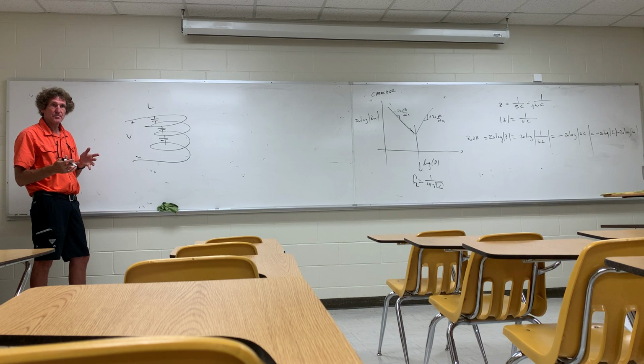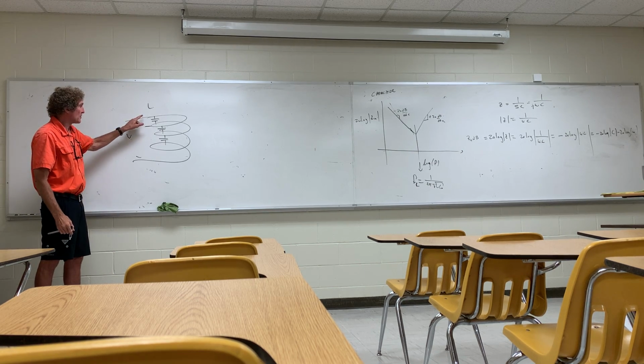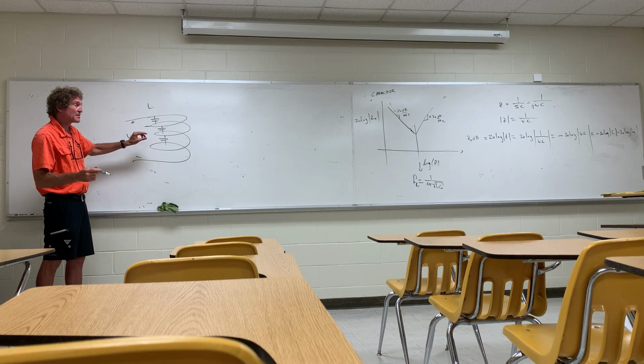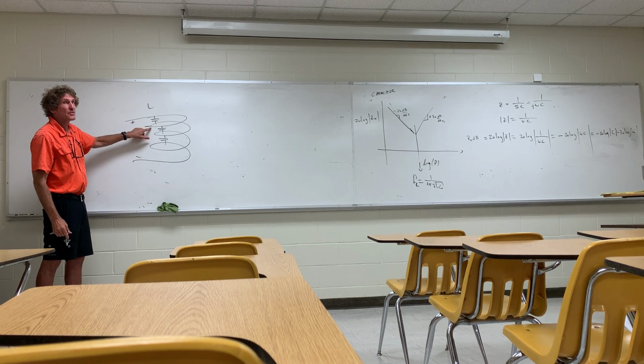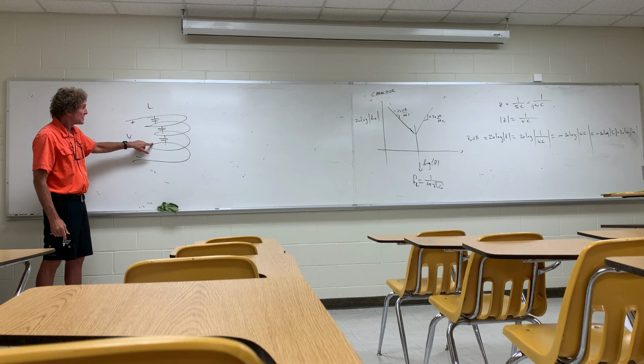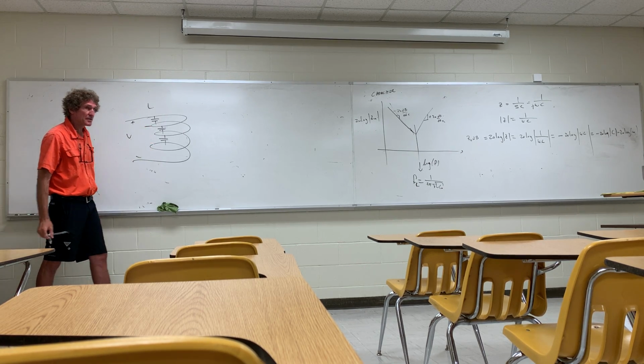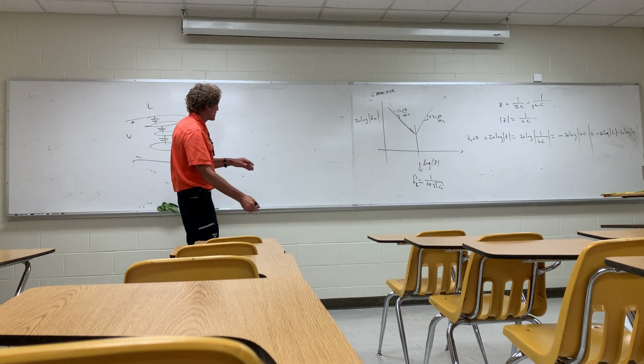Does that make sense to you? There's got to be a voltage difference between top and bottom, and since there are many turns, there has to be a slight voltage difference between the first turn and the fifth turn. And if there is a voltage difference, there will be a charge distribution, which is an effective way we model as a capacitance.